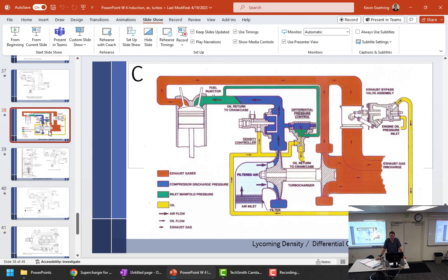So how do you know where you are supposed to go to find this stuff? If somebody overboosted their engine, where are you going to go to find out what to do? I mean, please tell me you're not going to go to YouTube or your class notes. Where are you going to go? Service bulletins, service letters, service instructions usually have all of that information for the engine. It's hard to remember where to go. Well, that's the thing. You have to remember where to go to find it. I know, it's not easy.